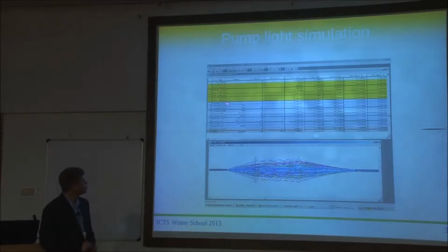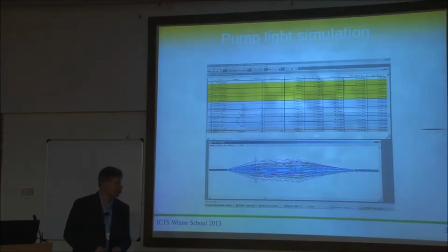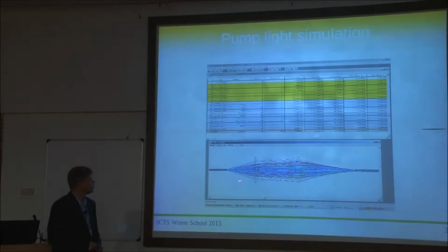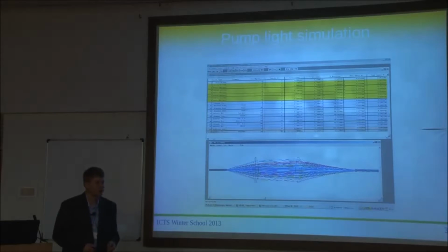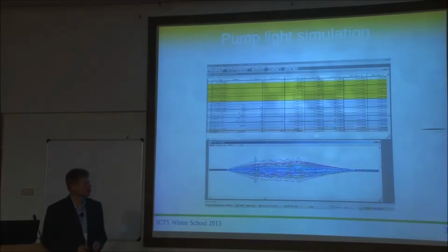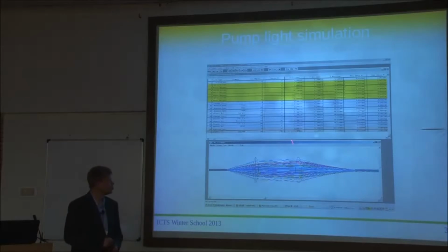What you can do is you put in all the parameters you know about your pump light source. You put in all the curvatures and materials and so on about your optical components. You put in all the parameters you know about your laser crystal here. Then you pick a certain amount of rays, and it does an analysis that is not only geometrical optics, it's really doing wave optics, taking scattering into account, and also reflections, of course, and so on. Then it gives you the option to put virtual detectors somewhere, and just analyze what's going on there.